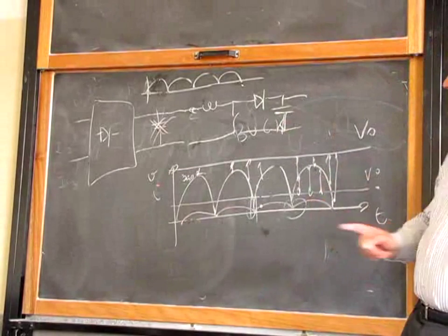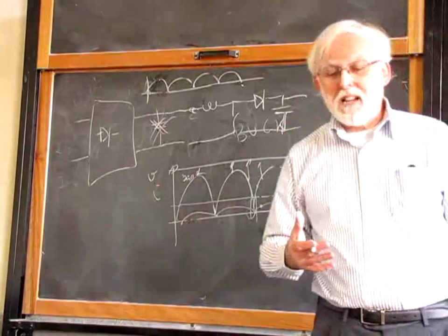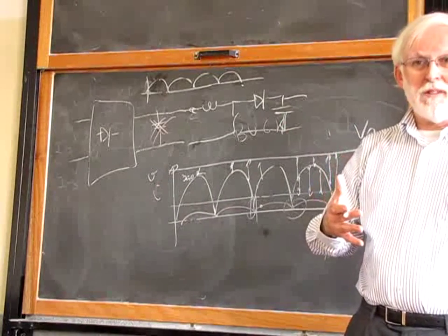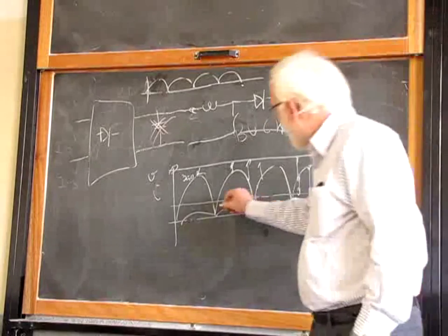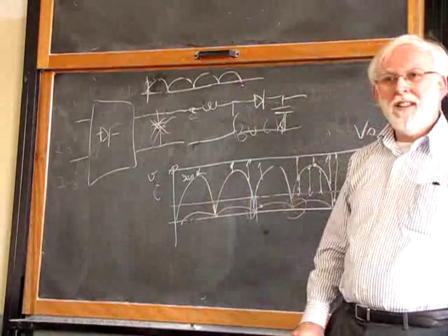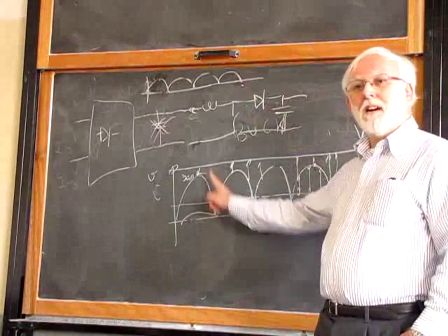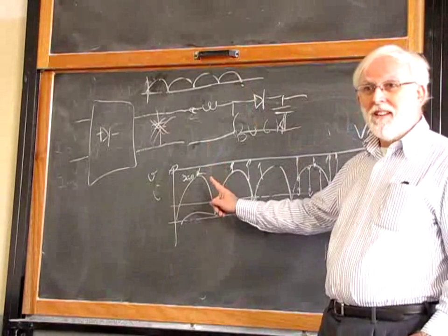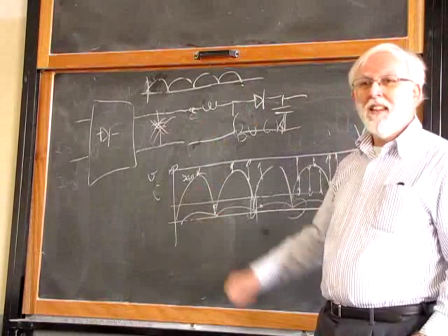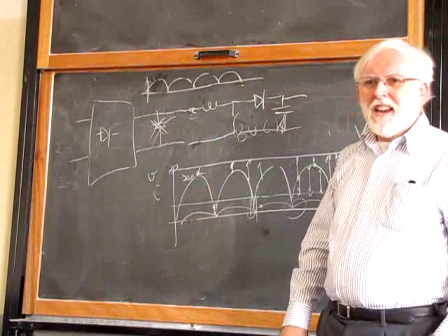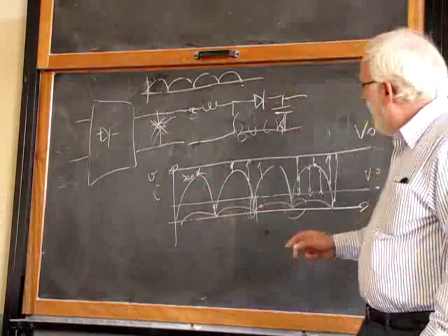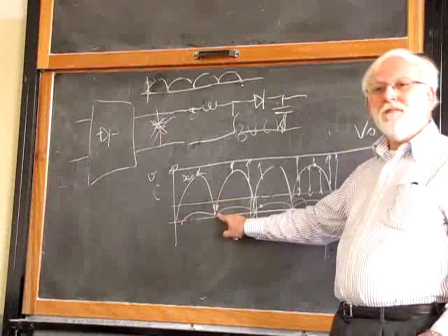But you remember that I told you the real practical boost converters cannot boost the voltage more than 3 or 4 times. Do you remember it? So what happens when I have here 30 volts? I have to boost the 30 volts up to 400 volts. That is a multiplication factor of 13. Can we do it? Can it make it? Yeah, it can make it. It's not very happy, but it can make it, because here current is very low.